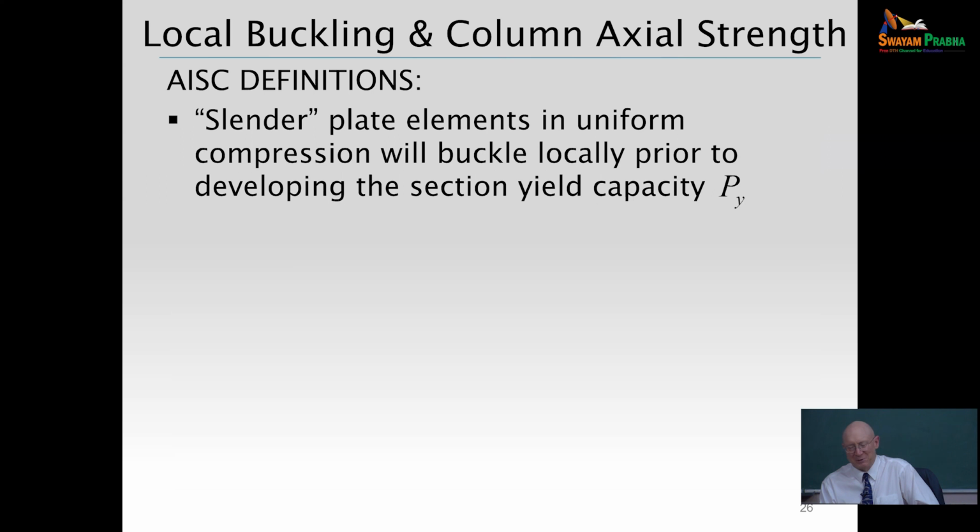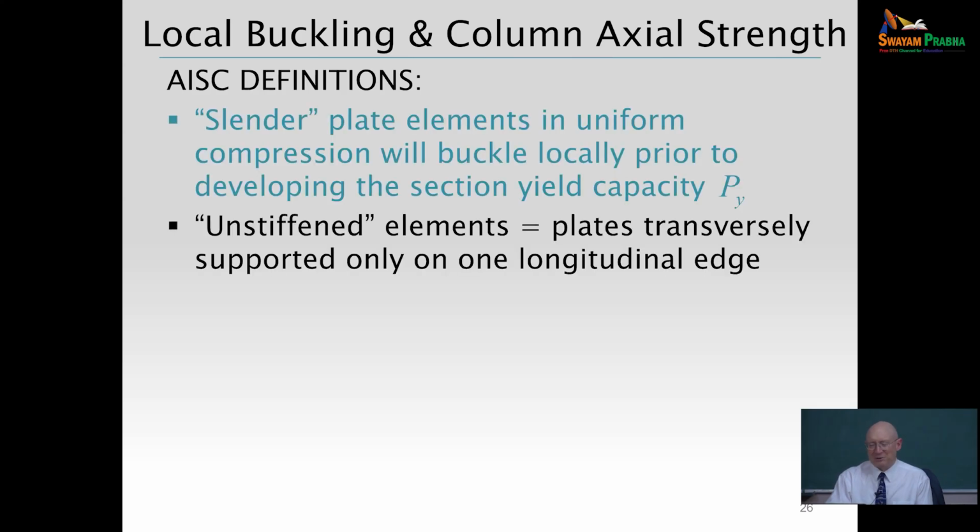it's something different than I was about to talk about. So we refer to a plate element as a slender plate element in uniform compression if we could potentially get buckling locally of that plate before we reach the yield capacity of the cross section. Okay, so would that be slender in the Indian Standard? Okay, yes.